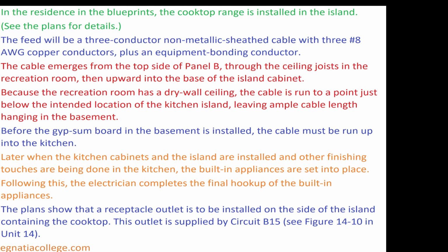The plans show that a receptacle outlet is to be installed on the side of the island containing the cooktop. This outlet is supplied by circuit B15, see Figure 14-10 in Unit 14.